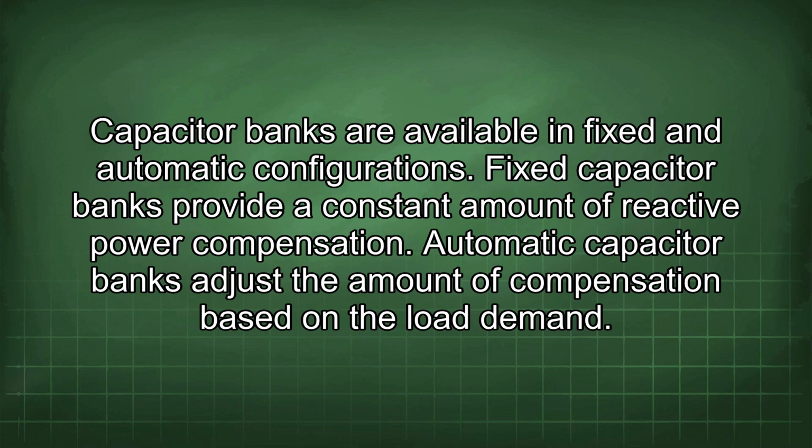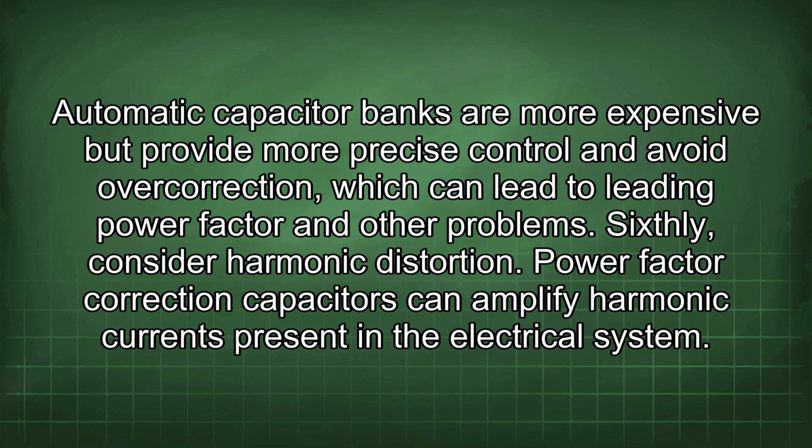Automatic capacitor banks adjust the amount of compensation based on the load demand. Automatic capacitor banks are more expensive but provide more precise control and avoid overcorrection, which can lead to leading power factor and other problems. Sixthly, consider harmonic distortion.